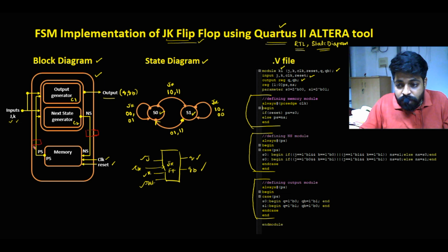This is also what we call a net data type, because the next state and the present state are two variables we didn't declare as an input variable or an output variable. That's why we define them as intermediate variables, using the net data type register.